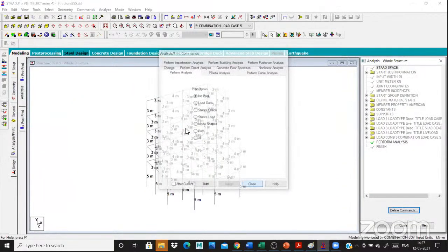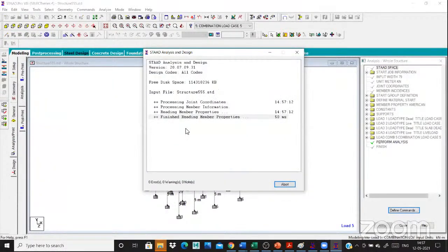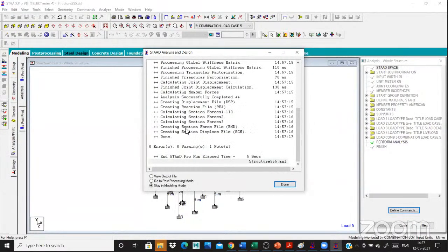That is the procedure. This is the difference between yesterday and today. Yesterday was a 2D structure. There was no floor. Today will be a 3D structure. So the floor is there. We will create the floor. We will apply the floor loads for these different one-way and two-way square slabs. Then I created the model and analyzed my structure. Then how to see the values? Post processing.